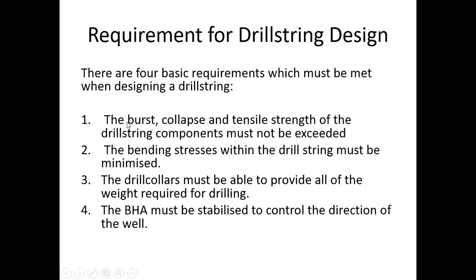First, you have to calculate the burst, collapse, and tensile strength of the drill string. We have to know at what pressure it can burst, what pressure it can collapse, and what the tensile strength of them is. Then, what are the stresses on the drill string at the current depth wherever it is drilling? How many drill collars are needed? And what bottom hole assembly must be stabilized to control the direction of the well?